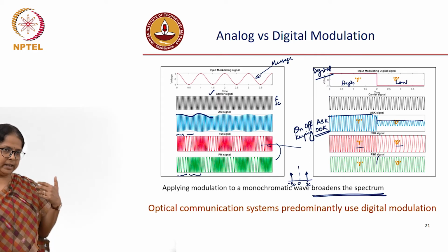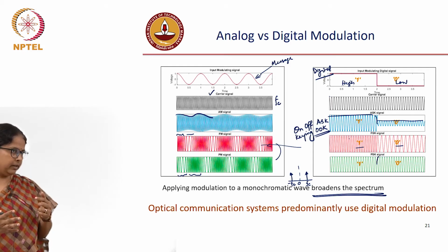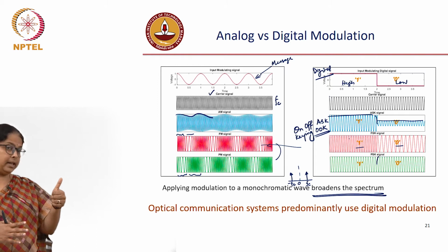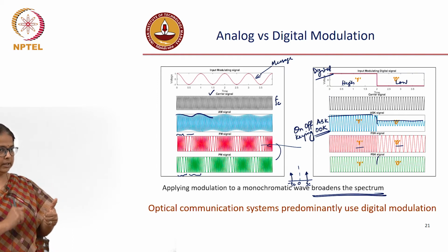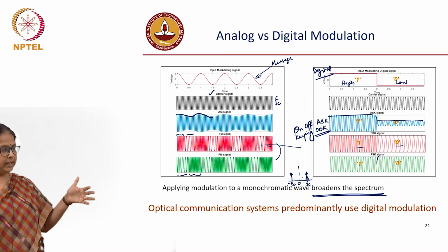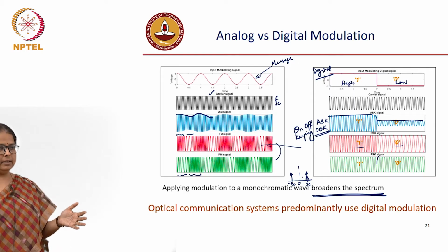For instance, chromatic dispersion is dependent on the bandwidth, it is dependent on the line width. You may get confused: should I use the line width of the carrier? In case of optical communication, the carrier is a laser. A laser will have a certain line width. Should I use that, or should I use the bandwidth of my entire signal? And the answer, as I have already given you, is that you should use the bandwidth of your entire signal.